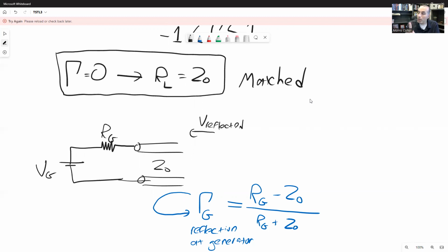But with enough ping pongs back and forth, it's going to settle out. And the magic is that this will always approach the correct solution to the circuit that we would have anticipated from basic circuit theory. It just gets there via this back and forth process. It's kind of magical if we think about it, because I haven't told the generator that it needs to produce a certain current and voltage in order to supply it to the load, but it's going to get there if you give it enough time.